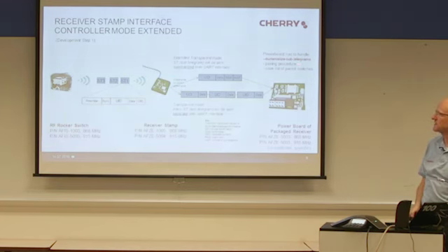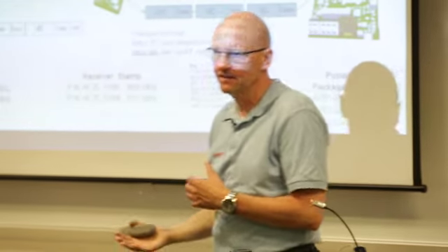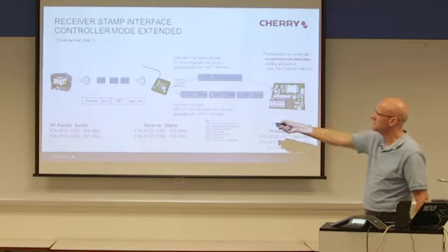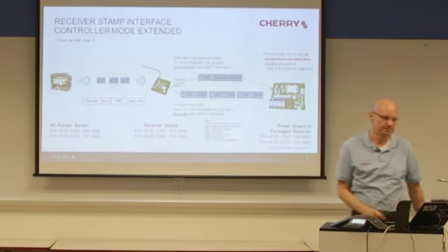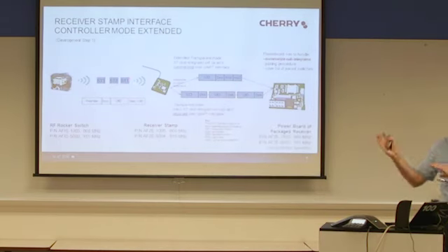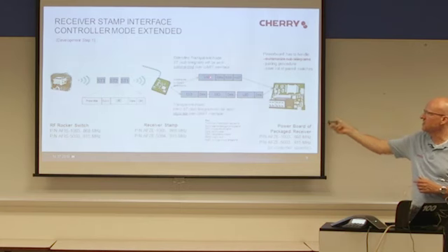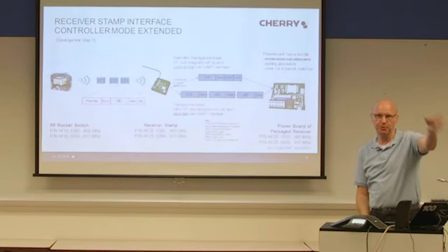So the power board has to handle, in a second step, not summarizing the subtelegrams, but the pairing procedure and saving the list of paired switches. So in the first development step, the intelligence of the RF stamp is that we summarize these 3 subtelegrams. So the power board gets only the information: switch 17 is pressed.